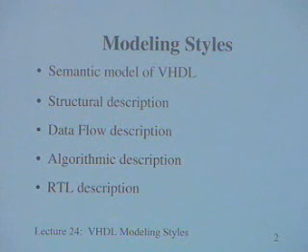As I said before, VHDL can be used for modeling, and VHDL can also be used for synthesis, and depending upon the synthesis tool you use, the tool may have restrictions on which level or style of description it supports. So you have to be aware of that, more so in case of synthesis, because there are a lot more restrictions in terms of what you start with. The structural description, as you will see, refers to describing the structure, which typically is a netlist of components.